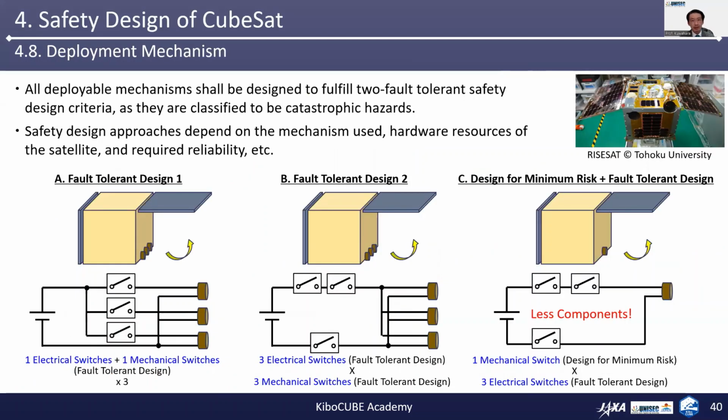Next, in this slide, we'd like to discuss the safety design of the deployment mechanism, which is also another very important topic. All deployable mechanisms shall be designed to fulfill two fault-tolerant safety design criteria, as they are classified to be catastrophic hazard. So safety design approaches depend on the mechanism used, hardware resources of the satellite, and required reliability, etc.